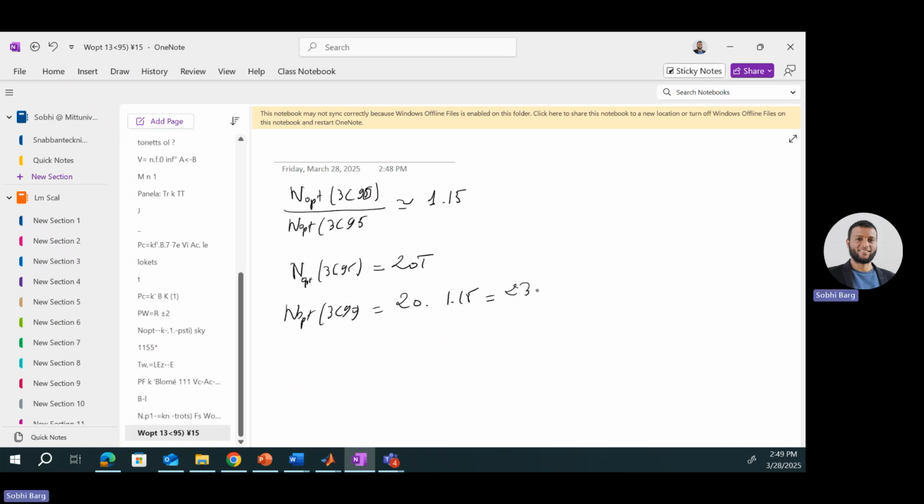So this is very far, 23 turns. What does this 23 mean? It means completely wrong results for the optimization. Why? You have 7 turns difference between the real optimum and the result given by the Frenetic Core Optimizer. If it is 30 turns instead of 23, that means higher winding losses. When you try to build your transformer, that additional 7 turns could lead to one more layer.